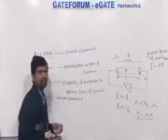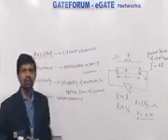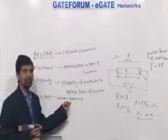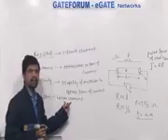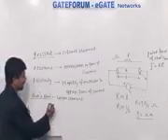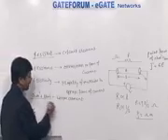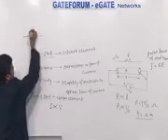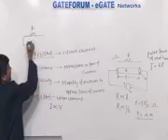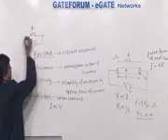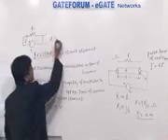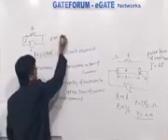Now what is the meaning of linear element? I can say that resistor, inductor, capacitor are linear circuit elements, because whatever the output is, that is dependent on your input excitation. I can say that current flowing through a resistor is proportional to applied voltage. So to any resistor, if I apply a forcing quantity as a voltage, then current of I ampere will flow. So I is proportional to V.